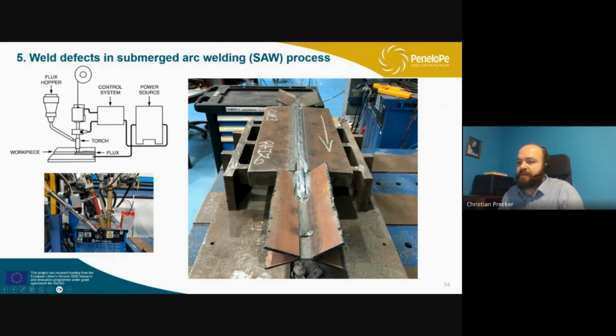Then we have here a camera to make videos of the process. Here we have a profilometer to see the surface of the weld. Okay, so we are acquiring data while we are doing the weld. And also we have access to the process data, like the electrical current that is used, the voltage, okay, in a time series signal.